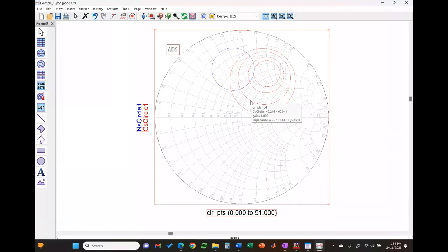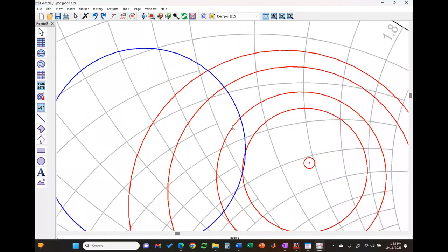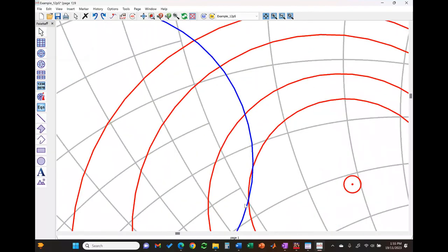This circle, the one I have the mouse on, has a gain of 0.5 dB. And you can see there are 2 intersections for the noise. So since we want to design for maximum gain, we know we can do better. So we go to the next gain circle at 1 dB. Again, there are 2 intersections. Maybe we can do better, so we go to 1.5. At 1.5, we also have 2 intersections. Maybe we can do better.